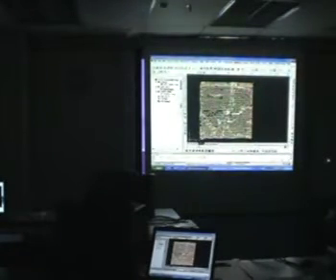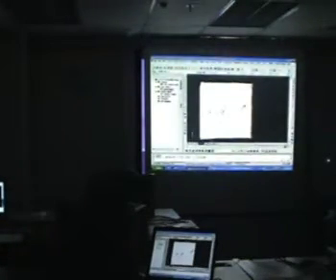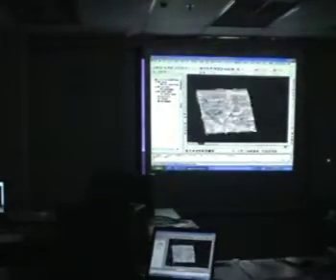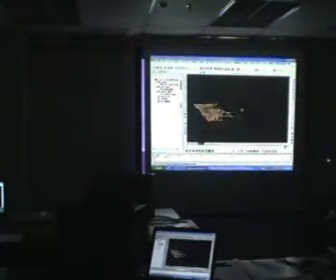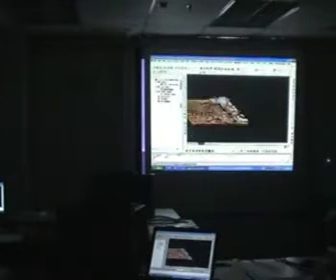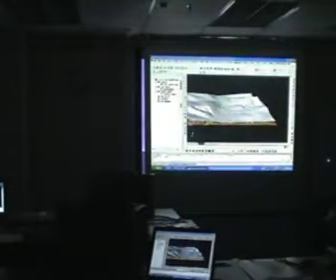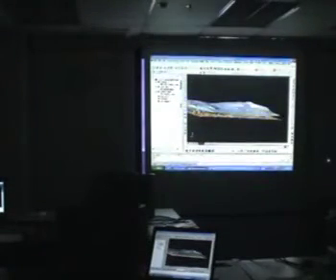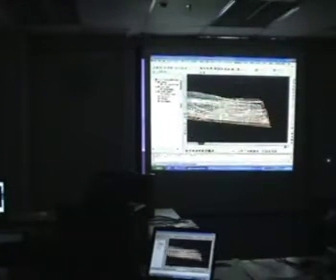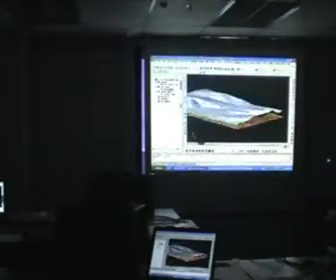Say I give a shade here, so it's a little bit clearer. You really see the lighting, how the light falls, how the light shadows fall. I'm just going to put this in 3D so you can see. Okay, this is what the surface looks like. And in this way, at least you can verify, okay, has the surveyor done his work properly? Maybe he made some vital errors on certain places. This is a way you can verify the information. And also as an engineer and a designer, you kind of get an idea, okay, how I should put the platform, how I should put the roads, for example.